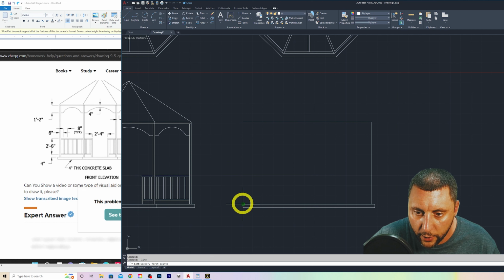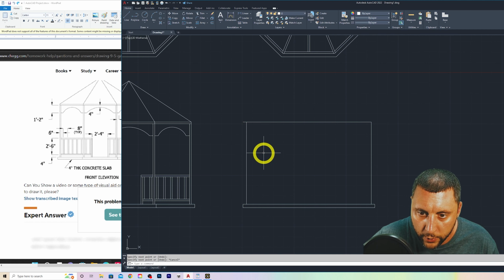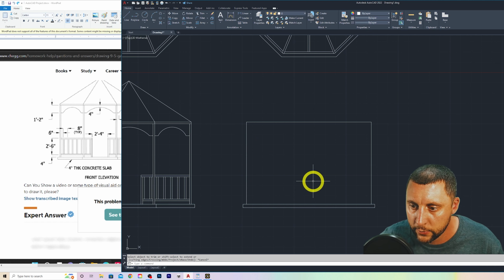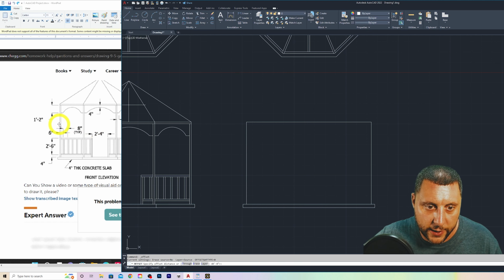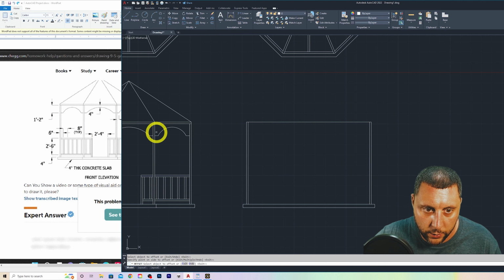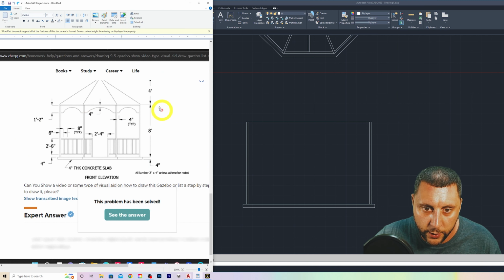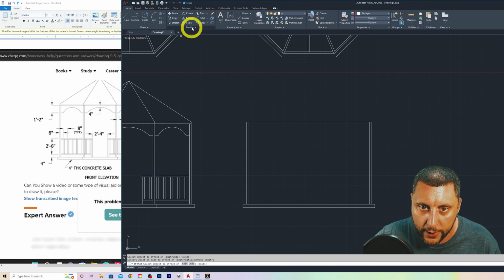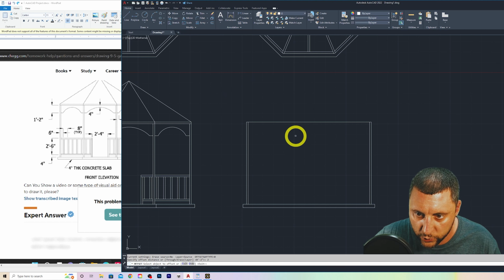And you get something like that to start. I'm going to do the same thing here. I'm going to slide 4, enter, and then go straight up. That gives me something to trim off again. 2x4 on the outside, so you're going to go 2 inches in. Offset 2, 2 in, 2 in. This top line that I have drawn up here right now is the top of the 8-foot line, which means we're going to go down 2 inches from there. So again, you're in the offset tool. You're doing 2, enter, and you're going 2 down.